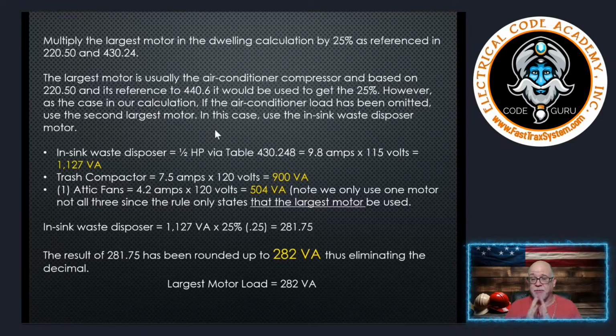If you take anything away from this, what we're saying is, look, this house has motors. And the rule in 430.24, when you have multiple motors, and we have multiple motors in this house, in this building, says to take the largest motor at 125% and the sum of all the other motors at 100%. Well, remember earlier when we were taking into account all these appliances? We actually took all the motors at 100%. Now, granted, we did apply some demands, but we've already accounted for these motors.